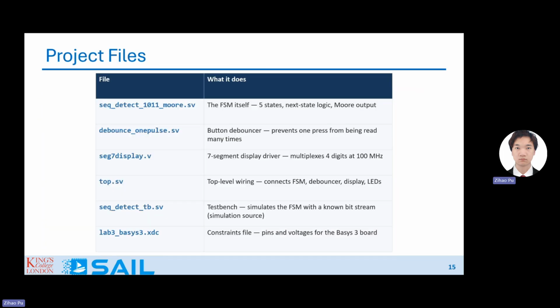It has a next state logic and output logic. And then I also put in a button debouncer, because the buttons don't really work well if you don't use debouncing, especially if you're going to use buttons on the coursework. I recommend you do debouncing just so it doesn't bug out and you don't know what's causing the issues.